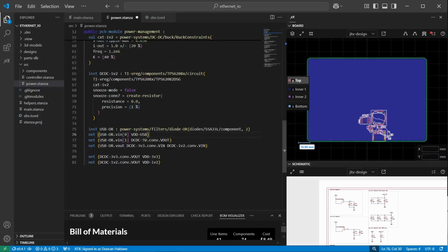So you want to use code that reflects your design intent, so the code that you write should look pretty cleanly like your requirements. We're going to use the 1.2 volts for the core on the Ethernet switch, and so that needs to come up before the 3.3 volts. So just like you might leave a comment in a schematic, except this is much more tied to the functional goal.